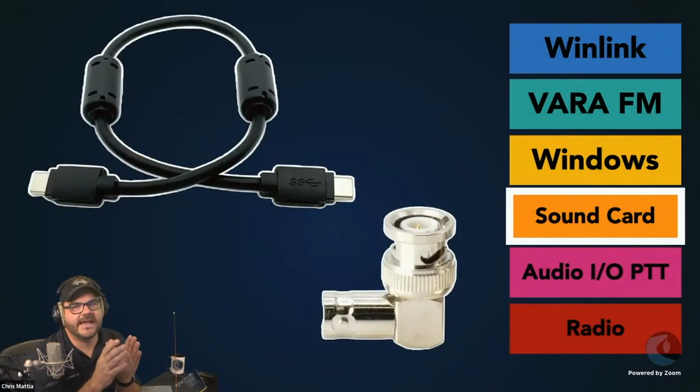When it comes to the sound card, you need to be able to connect your sound card into your computer. There's a variety of different cables that you can use, but this is one of the places that also gets people kind of messed up. When you connect, you want the shortest cable that you can get, and oftentimes you need to have ferrite beads installed on the cable to reduce any RFI, because your cable, remember, is going to act as an antenna. It will pick up any of the RF that's being transmitted, and it's going to go into your computer and make kind of a mess of things.